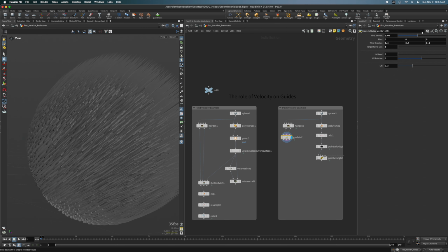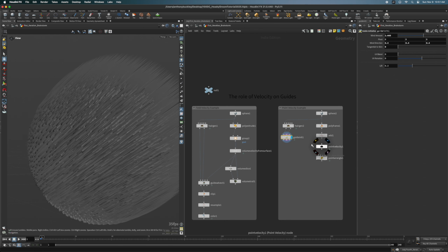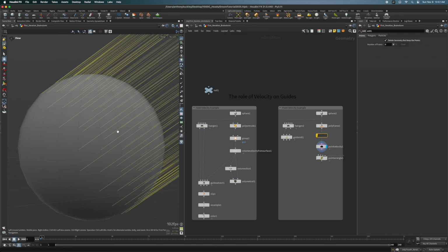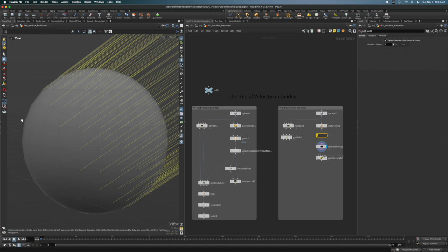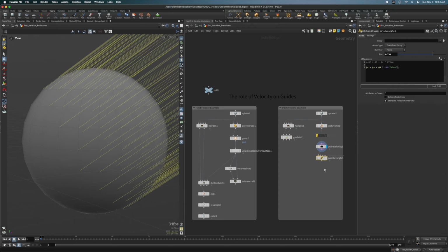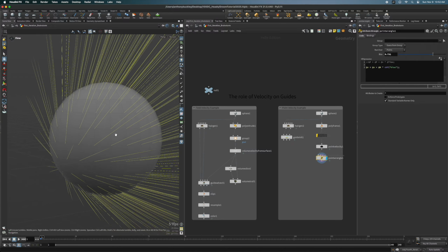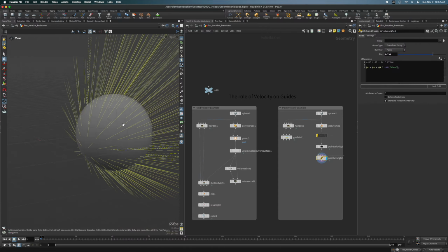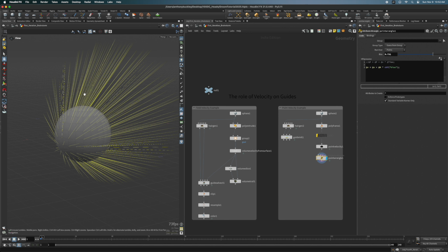Now, these are exactly like the trails here in this point velocity in that they are penetrating through. Here, I'll turn off this add node. And you can see that all those trails, even starting on this side, are just penetrating through the geometry. One of the benefits with this guide initialize is that you can avoid this using a tangential to skin slider. Now, I'm going to attempt to replicate that with this wrangle in which I take the normals and combine them with velocities, and this kind of stops those trails from punching through the surface, but it also doesn't bend very well going along the tangent.